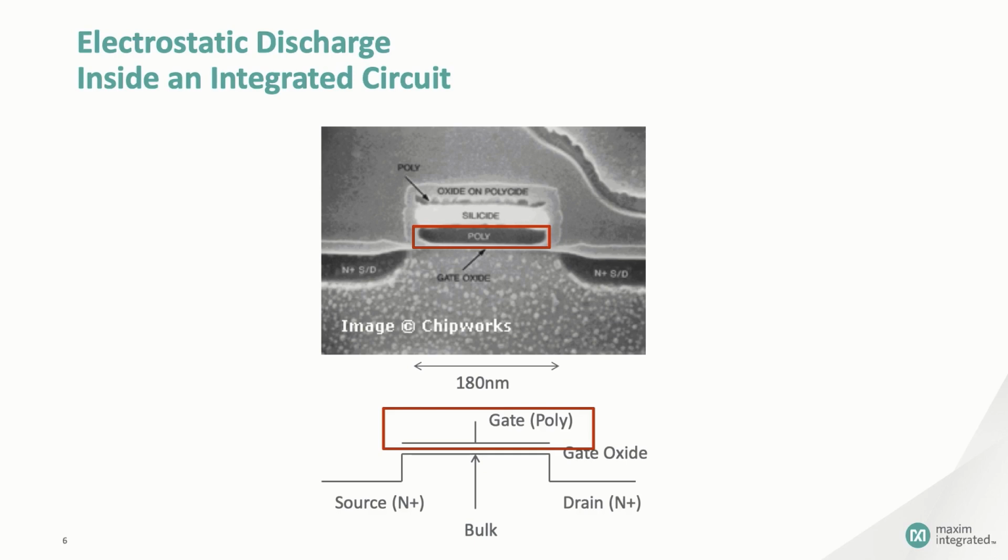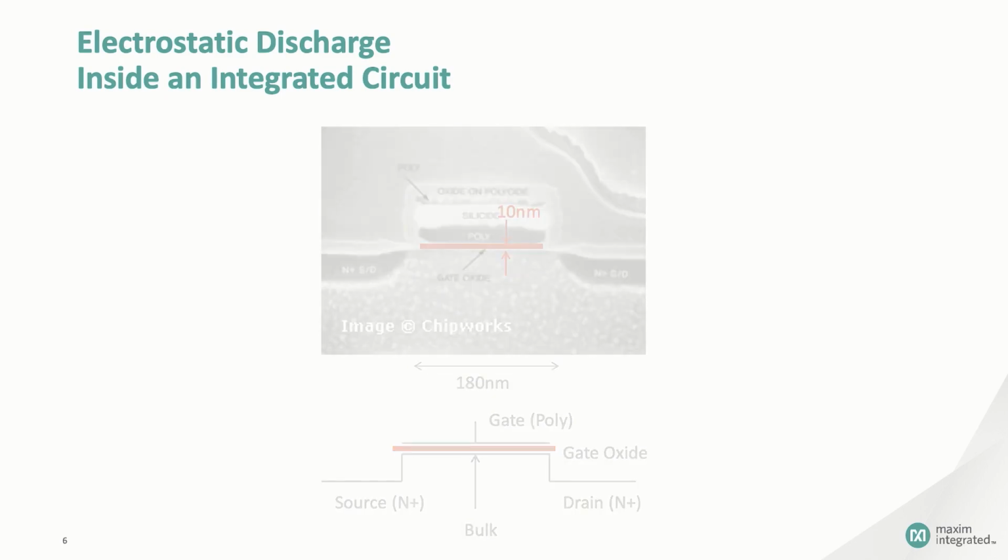All well and good. But to maximize the influence of the electric field on the channel, that gate insulator has to be thin, perhaps as thin as 10 nanometers. So that's the struggle. We need to get a gate insulator as thin as it can be, but also with as much dielectric strength as possible. Okay, it's time to break out the math.